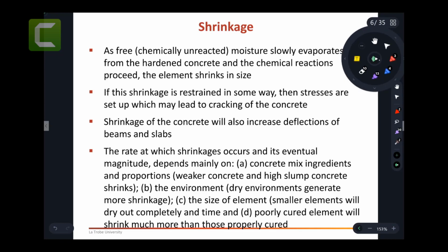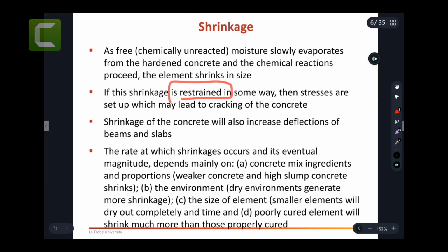So that was just giving you an understanding about what we mean with restraining, because all the slabs are restrained, whether sitting on the ground or suspended on walls or columns, and that restraining mechanism will resist the shrinkage, and then it will cause stresses, which, when the stresses again go over what the concrete can take, and last week we talked about the 3 MPa. You remember the 3 or 4 MPa? The 3 and 4 MPa is the maximum tensile stresses.